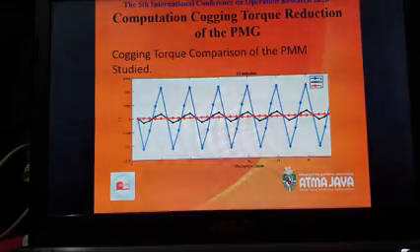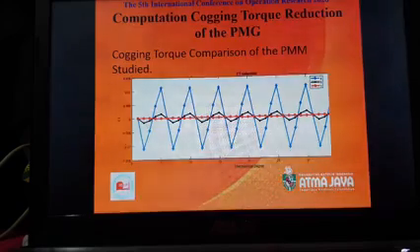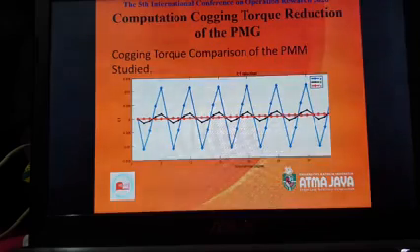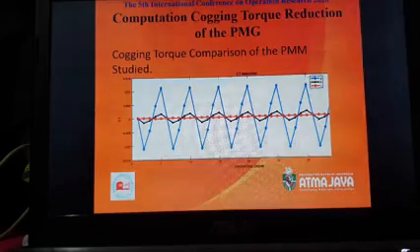In addition, another benefit of employing the magnet shaping combined with 3 dummy slots in the stator core is that the magnetic flux density in the stator and rotor core also declines, leading to eddy current losses also becoming smaller compared with the initial structure.